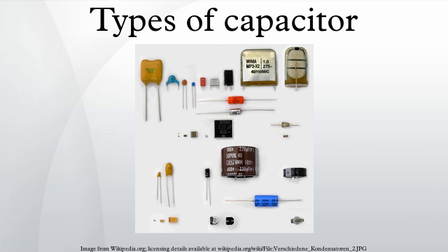Aging. In ferroelectric class II ceramic capacitors, capacitance decreases over time. This behavior is called aging. This aging occurs in ferroelectric dielectrics, where domains of polarization in the dielectric contribute to the total polarization. Degradation of polarized domains in the dielectric decreases permittivity and therefore capacitance over time.